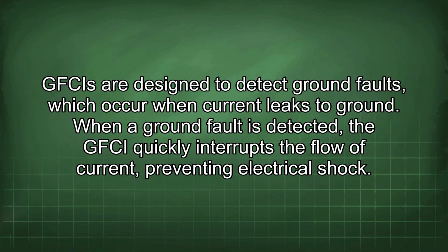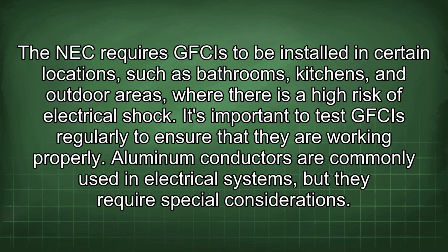GFCIs are designed to detect ground faults, which occur when current leaks to ground. When a ground fault is detected, the GFCI quickly interrupts the flow of current, preventing electrical shock. The NEC requires GFCIs to be installed in certain locations, such as bathrooms, kitchens, and outdoor areas, where there is a high risk of electrical shock. It's important to test GFCIs regularly to ensure that they are working properly.